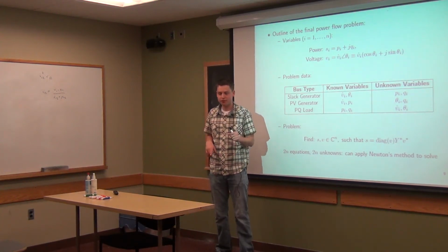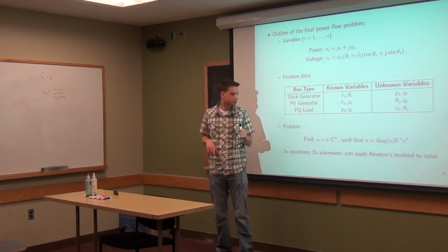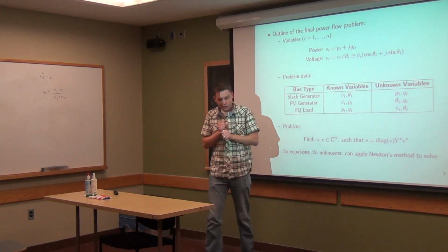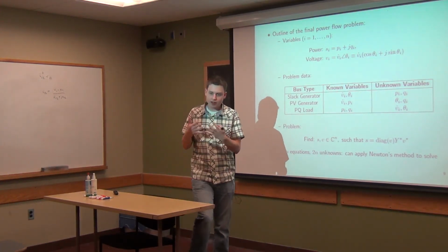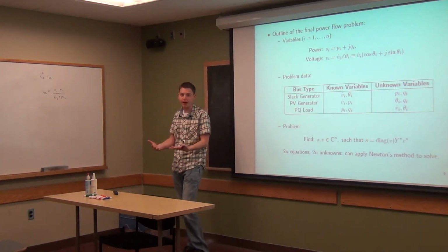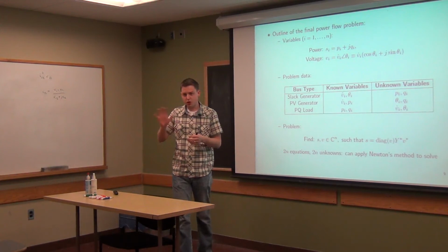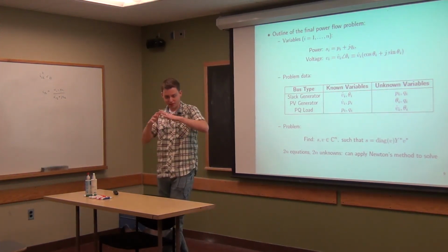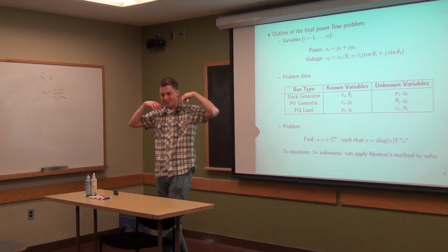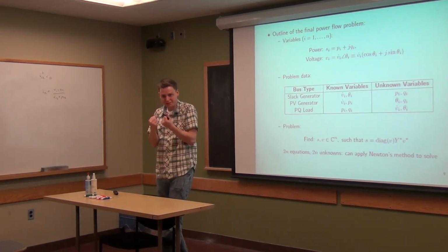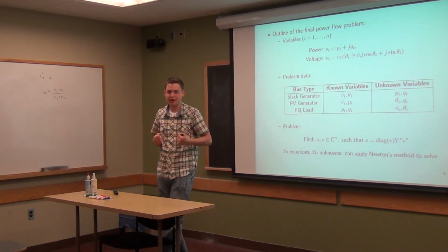Yeah? So you said the slack generator assumption is not actually what happens physically? Yes. So what actually does happen? Well, what actually happens is that when there isn't enough real power, and this is sort of what I talk about with generators, if they aren't generating enough real power, they will start slowing down, right? Their frequency starts slowing down. If they're not generating enough power, they don't have enough torque to pick up what's being consumed by everyone, so they're going to have to start slowing down.